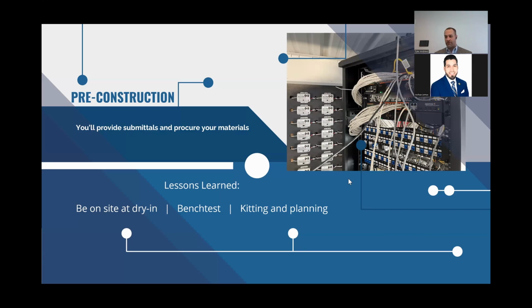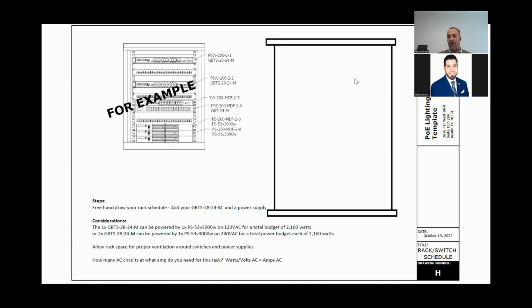And you need to account for space so that air can flow around them, unless you're going to force air in there. But whatever you do, don't back this thing into a wall and enclose it, because it will generate heat and it does get hot. So yes, there is a heating requirement that you need to make sure you deal with.